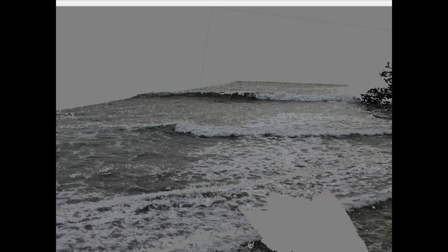You want to shoot with a high enough speed, the old thing of f-stop and ISO and aperture, shutter speed and ISO. You want your ISO nice and low so that you've got a good, crisp, sharp picture, but you also want enough light to expose it properly, and a fast shutter speed, and an f-stop that allows you a certain amount of depth of field, which ideally is infinity and beyond, and a few other rules. But the most important thing for PhotoScan or any other photogrammetric thing is to get the right amount of overlap and to turn the camera plane.